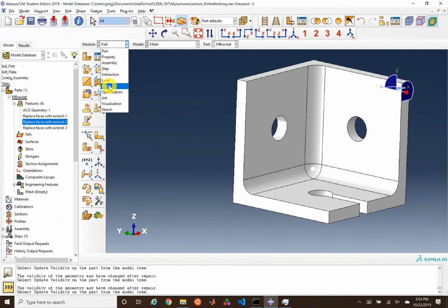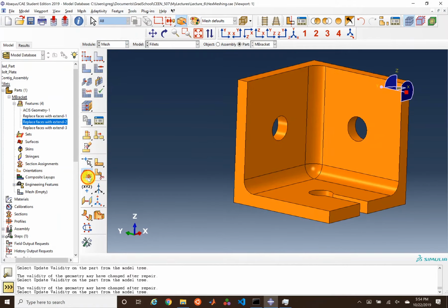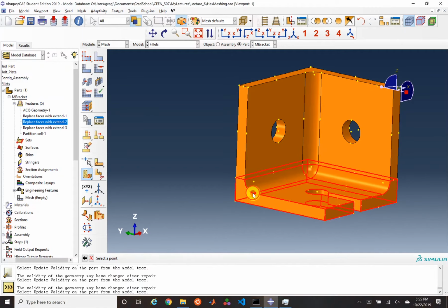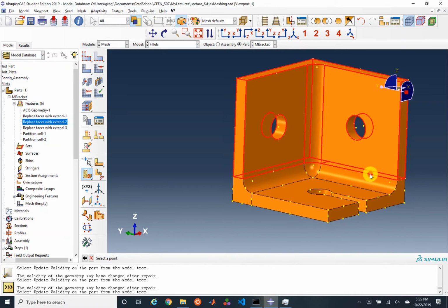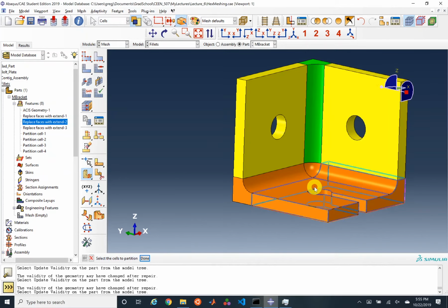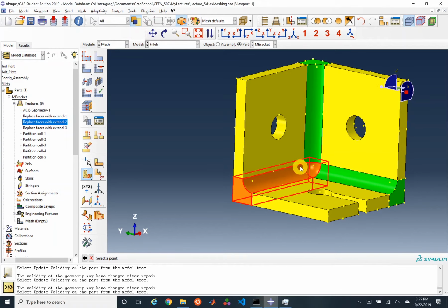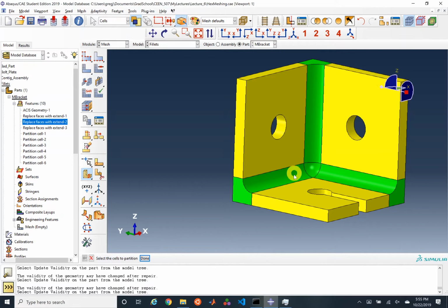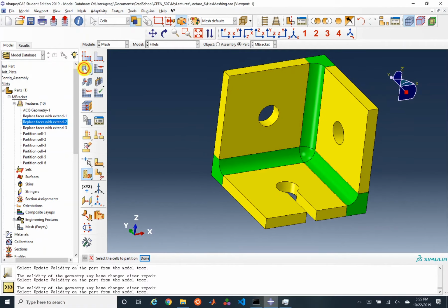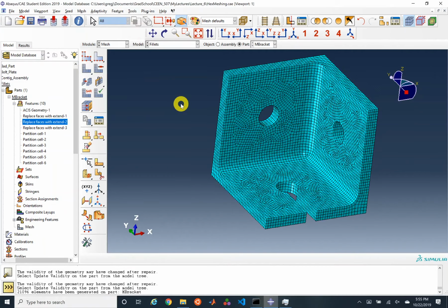But if we now try to mesh this geometry, we can take our same kind of approach of chopping these one by one. Right, so very few cuts here. I've got this hex meshable geometry. And if I mesh it, no tie constraints were needed.